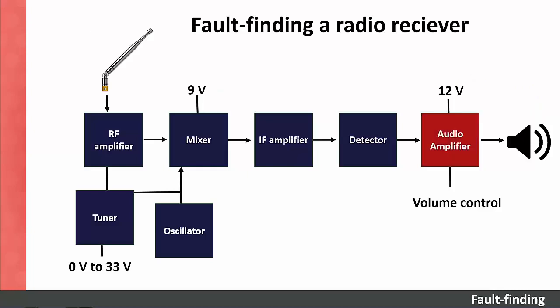It has to be the audio amplifier stage, because the sound entering the antenna is generally weak, gets amplified just a little by the RF amplifier, and then sent to the output. The signal needs amplification, which is not happening. That's why the volume at the speaker is so soft. The first thing to check is the supply voltage to this particular section of the radio using a multimeter. If it is missing, the problem must lie in the power supply section, which is responsible for supplying the 12-volt or an open circuit resistor that is normally connected in series from the power supply to the amplifier.